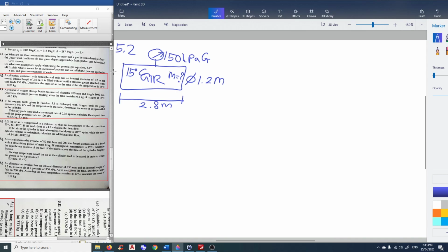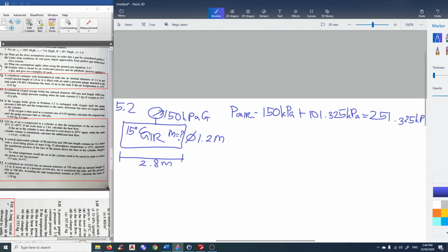So again, conversion. PA is 150 kPa plus 101.325 kPa, you'll have 251.325 kPa.